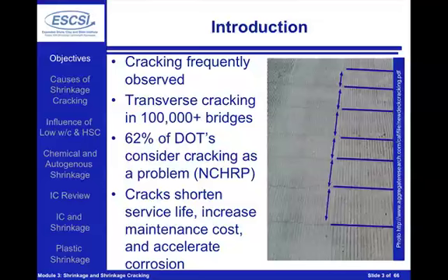The reason is cracks can shorten service life, they can increase the maintenance cost, and they're going to accelerate corrosion, which has the potential to reduce the service life, impacting sustainability and the life cycle costs associated with that part of the infrastructure. In addition, in many cases, cracks are unsightly. What we're talking about here is not eliminating all cracks in concrete structures, just the cracks that can be avoided, due to thermal cracking or especially shrinkage and water-induced cracking in these systems.